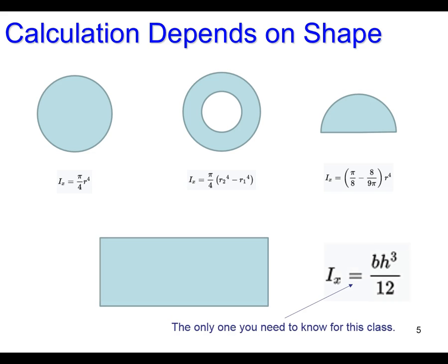The equation for calculating the area moment of inertia of a rectangle is the base times the height cubed divided by 12. So as long as you know the base and the height of the rectangular cross-section, you can calculate the area moment of inertia. There is one trick though. Remember from the presentation on centroids that a neutral plane exists over the centroid of a shape? As a reminder, this neutral plane delineates the place where the compressive forces change to tensile forces. Please review the presentation on centroids if you don't remember what all this means.